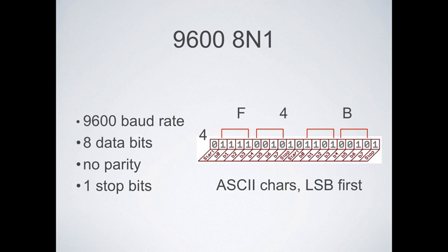So going back to our example, our first 4 bits of data are 1, 1, 1, 1. Our second 4 bits are 0, 0, 1, 0, followed by a stop bit, which is going to be 1. So that's our first serial packet. And if the sender or the transmitter says, I'm transferring this least significant bit first, what are we sending?